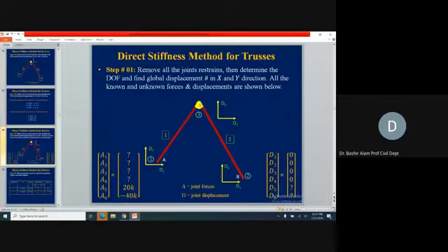If we start from here, this is joint 1, so this will become D1, D2. Now your reduced matrix will come to the left top. And if you select this free joint in between, then these coefficients will come in between, and you will be looking for them. Where are those free ones? We need to move in an organized way. We will take an example where it will be accommodated in the left top corner.